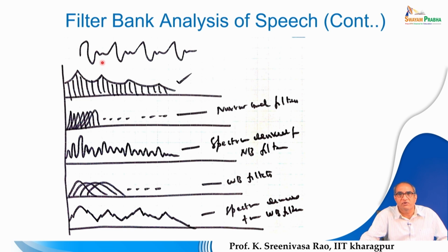So, therefore, if you want to analyze the frequency domain of a speech signal, you need to analyze shorter segments, where we assume that the speech characteristics are stationary. So, here we take some 30 or 40 milliseconds of the speech signal, and with the discrete Fourier transform tool we can compute the spectrum.